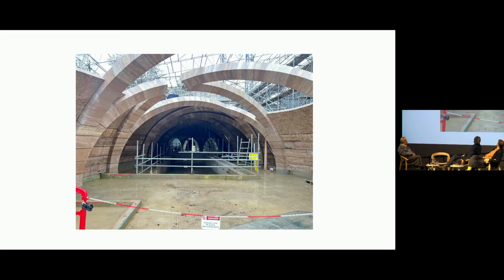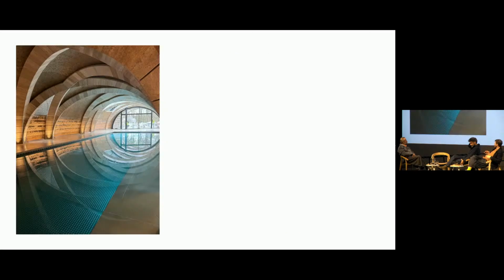So you can see that thing standing there before it's buried. The walls here are about 100 millimeters thick, and then the ribs are reinforced stone elements. But predominantly, it's 100 millimeters of unreinforced stone. Had that been a traditional rectangular concrete structure, it would be 600 millimeters of concrete to span across the top and 600 millimeters of concrete on the side. So massive carbon reduction achieved by being thoughtful about the form of the structure.